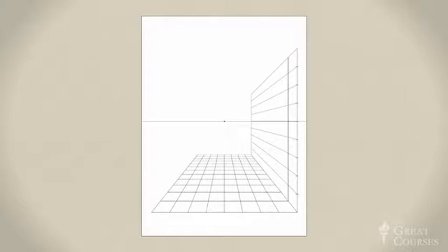Line up your straight edge along the diagonal of the bottom foreshortened square. Then mark the traverse of the extended diagonal on the receding diagonals. Once again, I've used a continuous line so it's easier to see. You can use both the horizontal recessions on the floor and the diagonal to draw the vertically receding rows of tiles. They should agree. When you get to the 8th row, you can repeat the use of the diagonal to find the final 4 recessions.